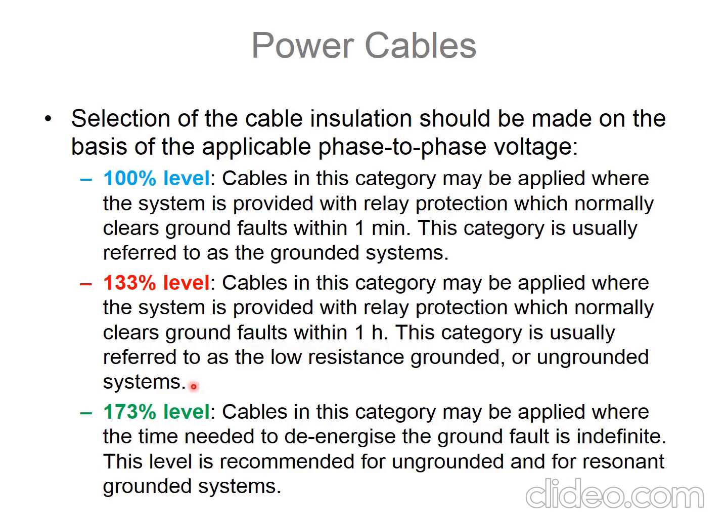And for the 173% level, the time needed to de-energize the ground fault is indefinite. So this level is recommended for ungrounded and resonant grounded systems.